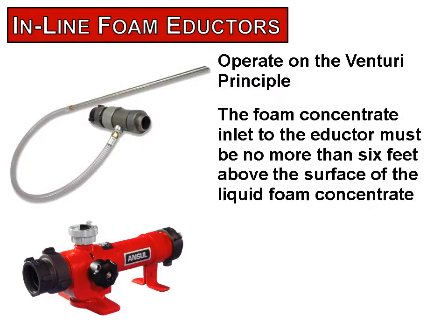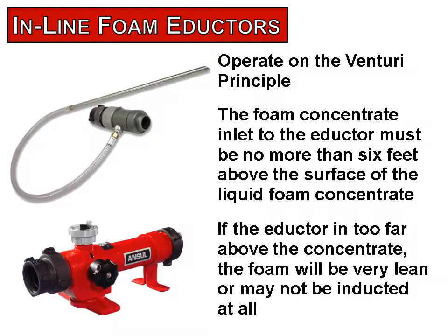The foam concentrate inlet to the inductor must be no more than 6 feet above the surface of the liquid foam concentrate. If the inductor is too far above the concentrate, the foam will be very lean and it will not be able to induct it into your hand line.